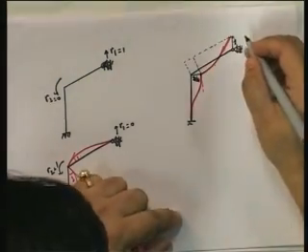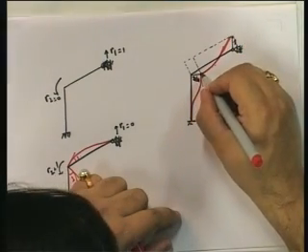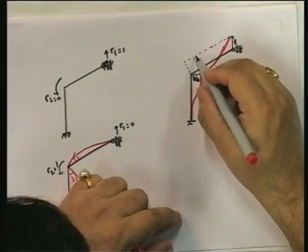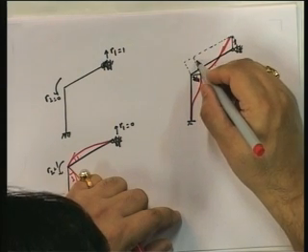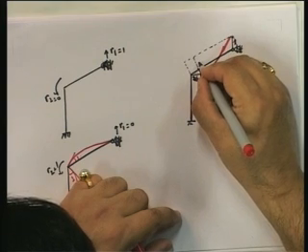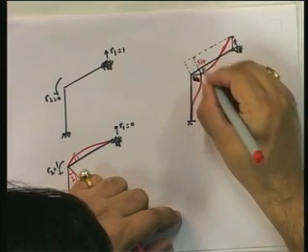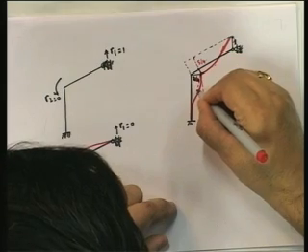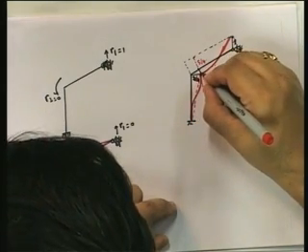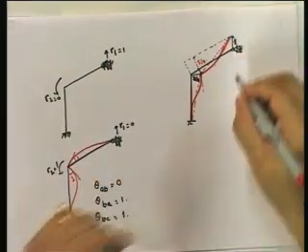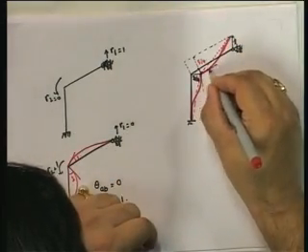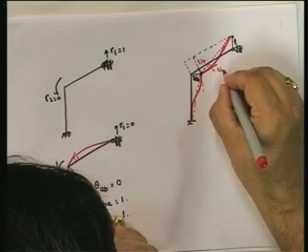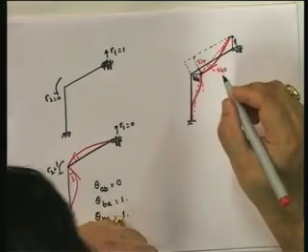So, this is 1, this is 3 by 4, and this one you can compute. Remember, last time we had done it, that if this is 3 by 4, then this is going to be equal to 9 by 20, and this is going to be 4/5, so that is 16 by 20. 9 by 20 plus 16 by 20, we had evaluated that this was equal to 5/4 from here to here. Okay. So, if I draw the chords, because ultimately it is the tangent from the chord, so my chord goes this way, and this is my angle. This angle, if you look at it, is equal to 5 by 4 divided by 10, so it's 5 by 40.